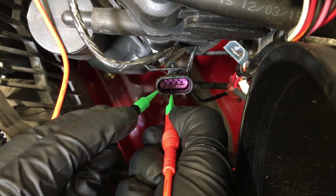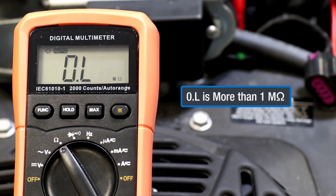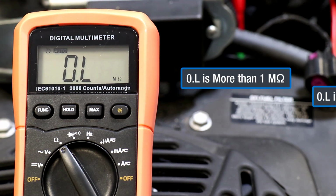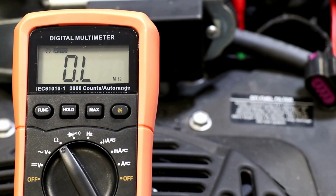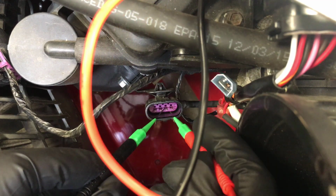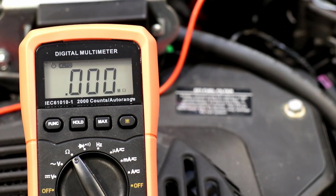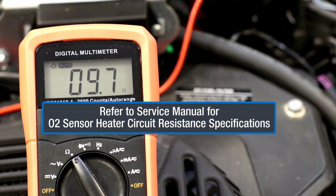If the resistance of the O2 sensor is 20 megaohms or higher, the meter will simply indicate OL. OL, or infinite resistance, is more than 1 megaohm and is a passing test result. Heater circuit resistance can also be measured, though a failure of this circuit is likely to result in fault code P0031 or P0032.